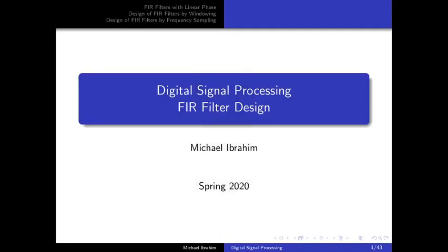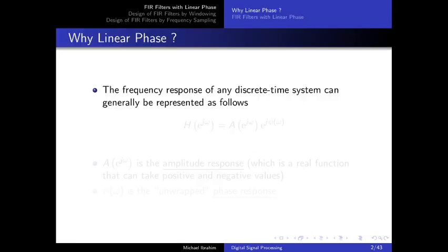Okay, so now let's go back to our slides and start talking about the design of FIR digital filters. In this lecture, we will talk about designing FIR filters with linear phase. Linear phase is a very important feature of a filter. If you remember in the previous lecture, we said that the phase response is either left completely unspecified or it's required to be linear.